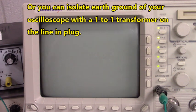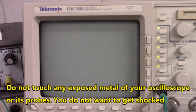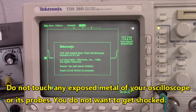When you do lift your oscilloscope from earth ground, be careful. Don't touch any metal on your oscilloscope, especially around the probes and whatnot. You don't want to get shocked.